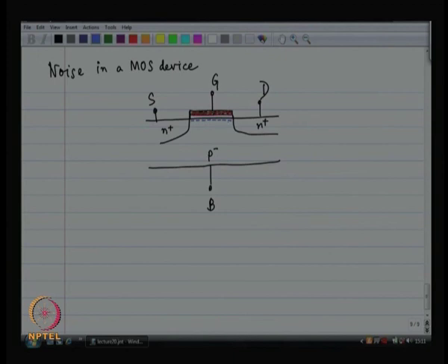Okay. First of all, the bulk of the MOSFET is going to get depleted of all the holes that were there. Now, considering that you have only lightly doped the bulk of the MOSFET, there were not too many holes to be depleted in the first place.